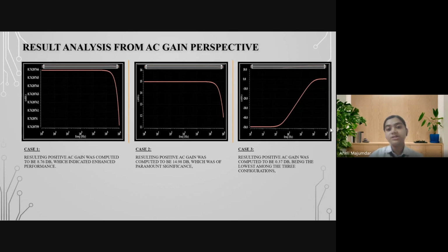The possible explanation is that the first 2 configurations, having 2 input pins, enhance even the smallest differences most significantly, thereby increasing the transconductance and leading to higher AC gain values. But for the unity gain buffer circuit with only 1 input pin, this is not possible, because the reduced input voltage also reduced the transconductance but increased the output resistance, and therefore such low gain was observed.